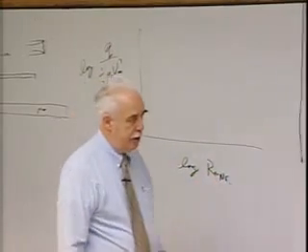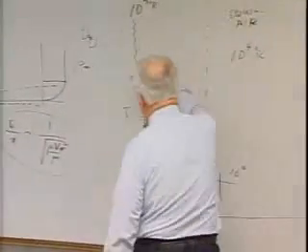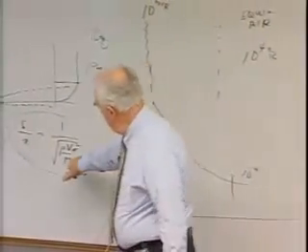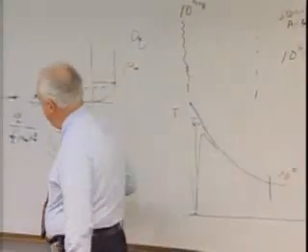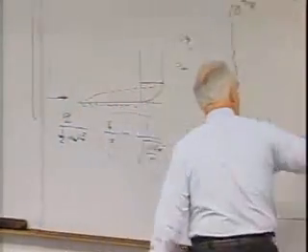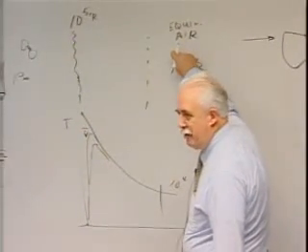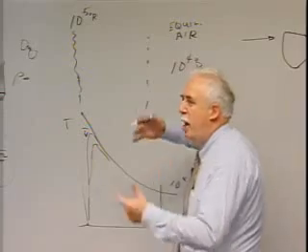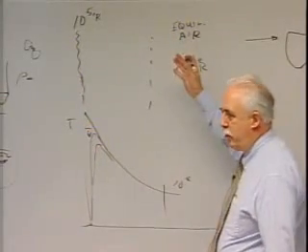All I do, as I go across the shock, the density, velocity, the mass flux is conserved, obviously. The viscosity is what changes. I'm going to use the normal shock equilibrium air viscosity, because that's more characteristic of everything going on in what the Russians call the protective shock layer.